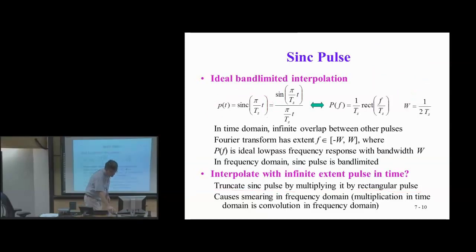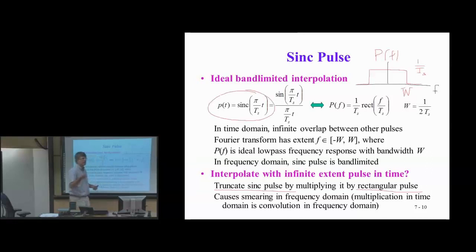All right, now that's the sinc pulse, which is the ideal reconstruction filter, but we can't use it in practice. We cannot implement the ideal one, but we can implement the truncated one. Now, even the truncated sinc has a drawback, and that is in the time domain it does not die out very quickly. The sinc takes its time, slowly going to 0 in amplitude.